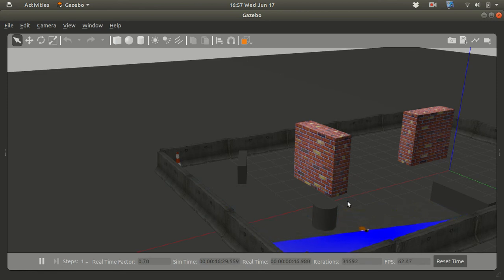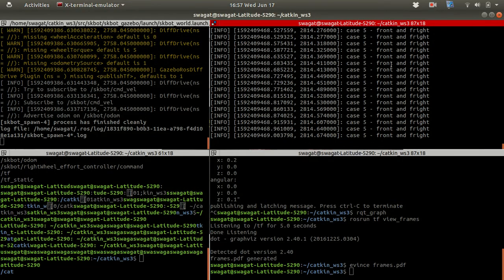This behavior can be utilized to generate the map autonomously. If you remember, in our last session we were moving the robot through teleoperation, the keyboard movement, and sometimes it is time consuming, because if you have a large environment you'll have to go around all the obstacles and get the scan. But now with this kind of algorithm, it is very easy to autonomously build the map. Alright, so this is also possible. So we'll stop it here.